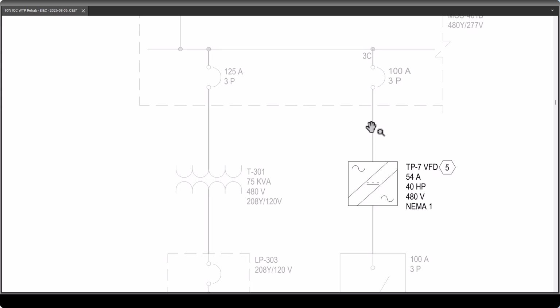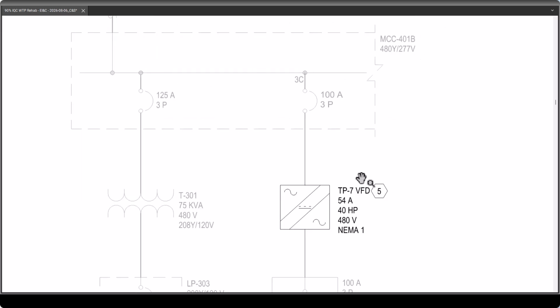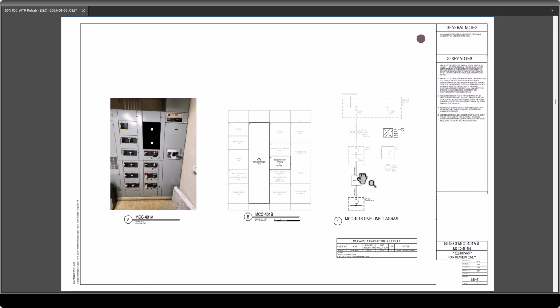Can I actually physically build this in the field? And that's a major step a lot of engineers overlook. The first time a contractor is staring you in the face in the field and they go, I can't physically build this. What were you thinking? And what do you want me to do now? Because I'm about to charge you a lot of money. That's a hard question to answer because you can't fit a 2-aught conductor in the back of a receptacle that you sized to 2-aught because of the voltage drop, right? It doesn't physically work like that. So, all right.